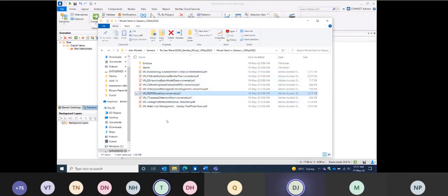And what we're going to do with that is take a steady state model, so a model that just runs one time step, and then we're going to do all of the work required to take it from that one time step through to a 24-hour full day simulation with everything that comes with that. So a diurnal pattern, as well as some pump on and off controls, which are very important, and then we'll try a couple of different scenarios, and we'll even compare the costs of those different scenarios as well. So you'll see the way they work differently.